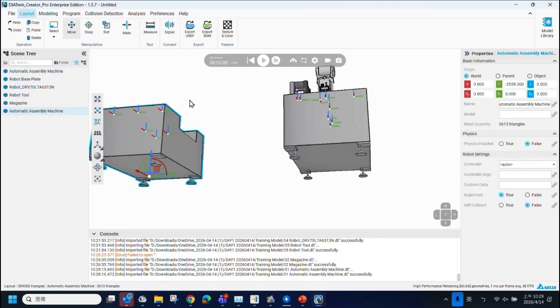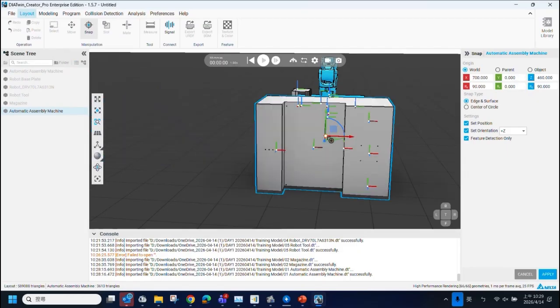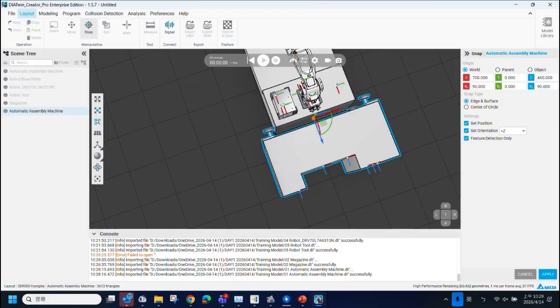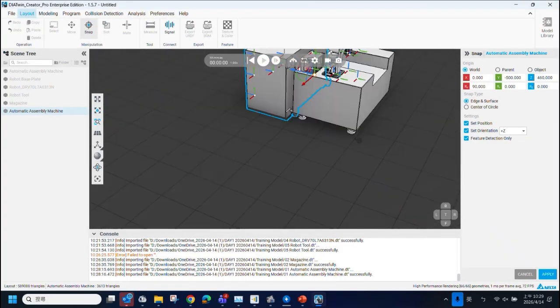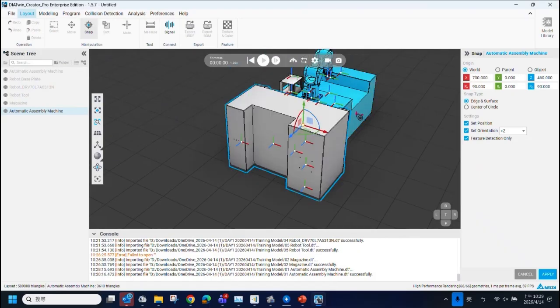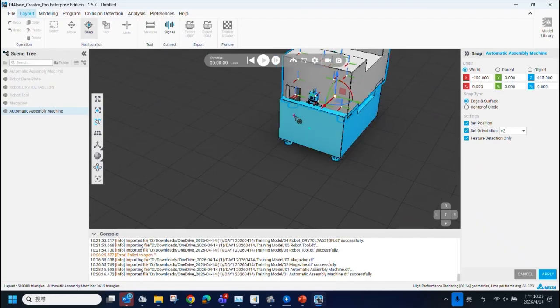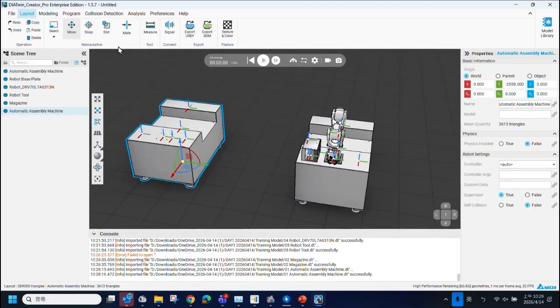You can see if I want to combine this frame to this frame, and you see, by using snap, there will be a problem because you can see the origin of this frame is at the center base of this one. So it is not easy for you to find the reference to combine these two frames. This is a problem. Also, if you need to create some base, it also takes time to create one right here and another right here. It will take time.